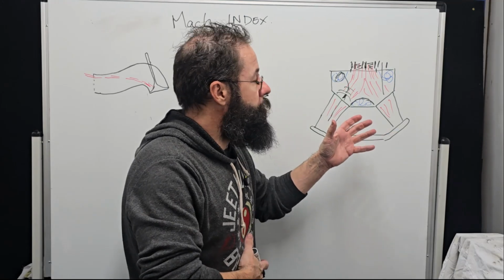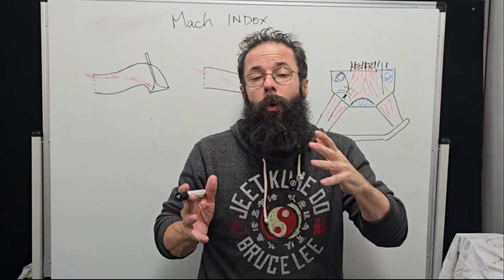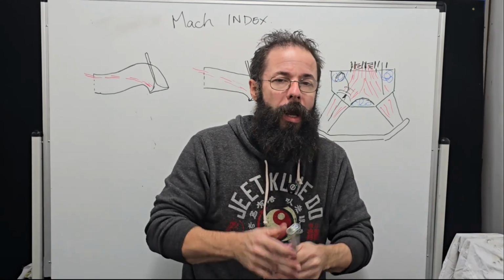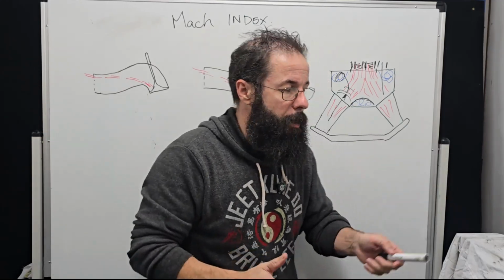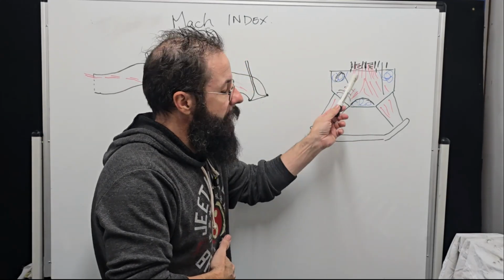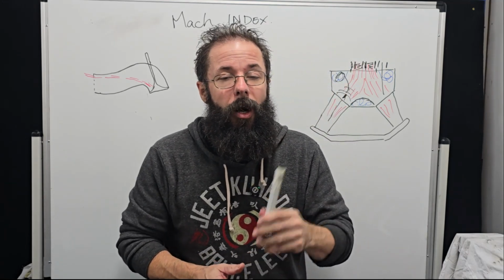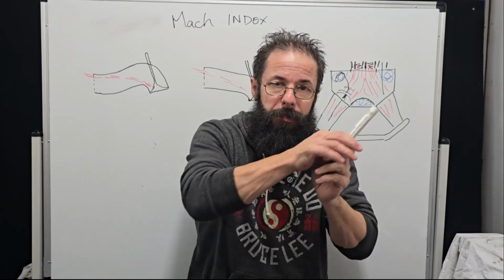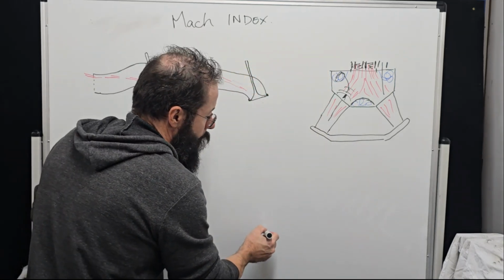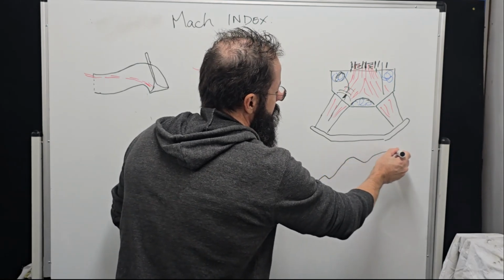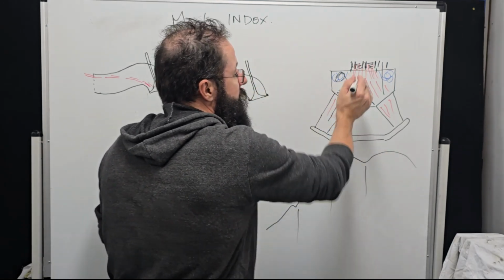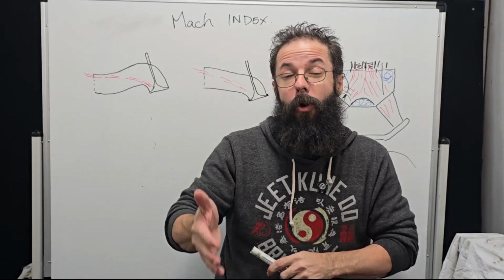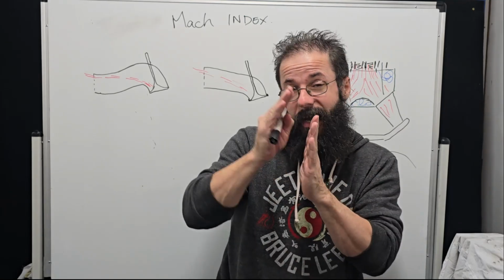This is why some compromises, some square corners actually can be good, especially in a tunnel ram, because they actually work for you in a way and give you a better, broader horsepower curve. And this is why. Any negative pulses, and you'll see these negative pulses on ITBs, generally 3 to 4 dips in the power curve. So if you're looking at an ITB horsepower curve, these are the negative waves that are coming back up, and you can actually see them on the dyno. You watch the pulses, and some of them actually throw fuel out the end of the runner as they're phasing in and out of that.